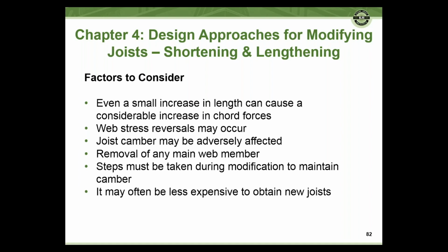Now we're going to look at what's in Chapters 4, 5, and 6. Chapter 4 covers design approaches for modifying joists if you're going to shorten or lengthen a joist. Factors you need to consider: when you're lengthening, even a small increase in the length can cause a considerable increase in chord forces.